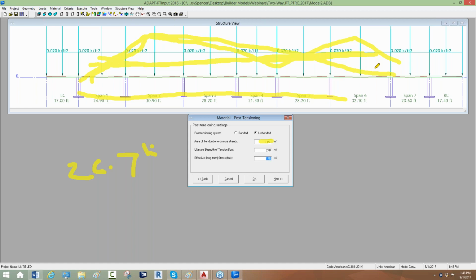If you're typically domestically here in the US, the engineers are designing per the effective force method, for example, for building design. The PT provider, supplier will actually do the calculation for the losses and meet the demand or the design forces on the drawings. In some places internationally, the engineer is responsible for not only the design but also the drawings of the tendon. So they're almost exclusively using calculated force method versus effective force.